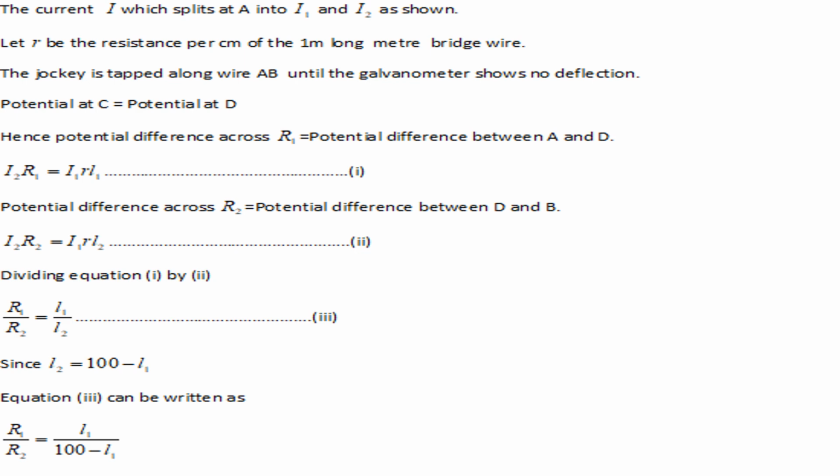equation 1 and equation 2, all you do is divide those two equations, and you get the balance condition of a Wheatstone bridge, which is R1 over R2 is equal to L1 over L2. So one part of the balance condition for a meter bridge is a ratio of resistances, while the other is the ratio of the lengths.